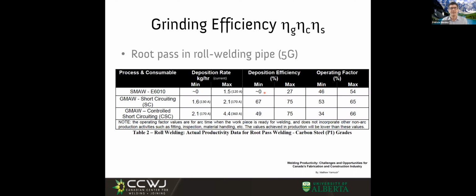What happens is that to get out these wagon tracks, clean up the slag, all those things, people grind it. One of the jokes is that people making root passes with 60-10 are more grinders than welders. Now the question to you is, if I'm going to be taking out more metal than I put in, why would I bother with putting any metal in?